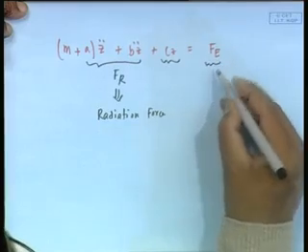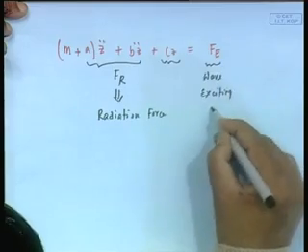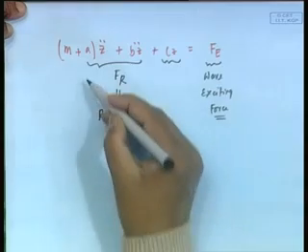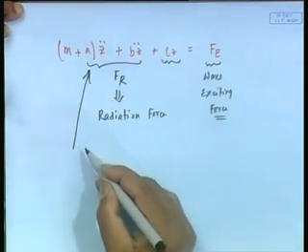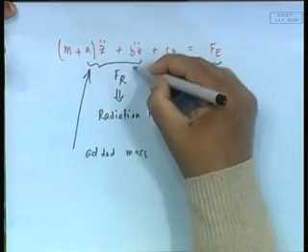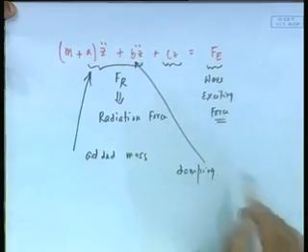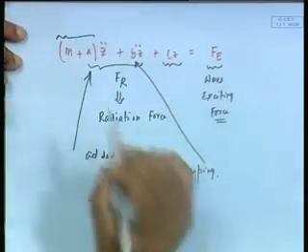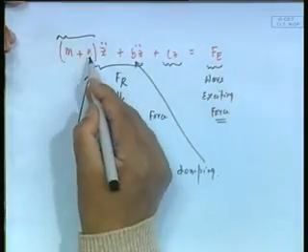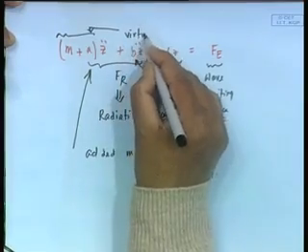This is what we call the wave exciting force. And this A, classically, everybody knows, is called added mass, and this B is known as damping. Some people call m plus a the virtual mass, that is, mass plus added mass as virtual mass. It depends on how you want to call it.